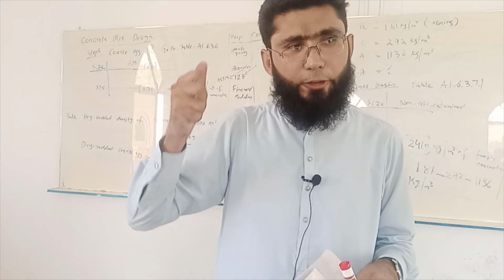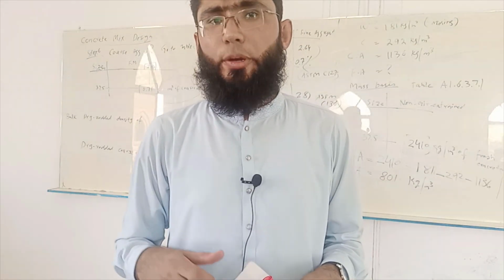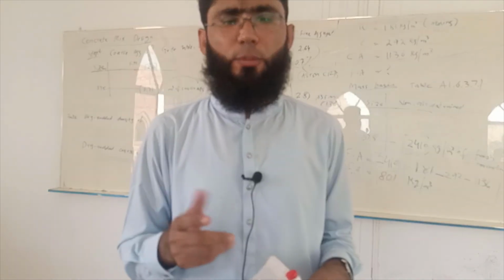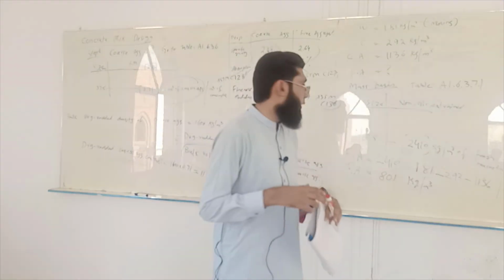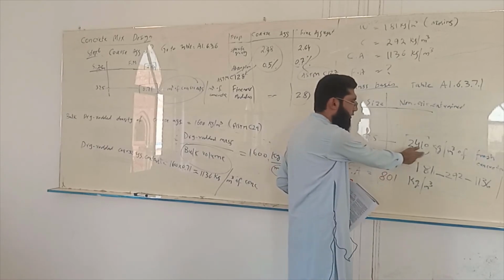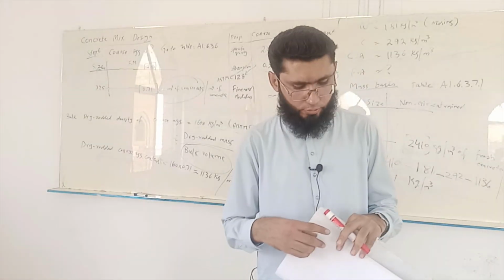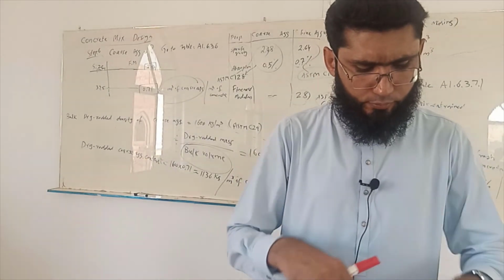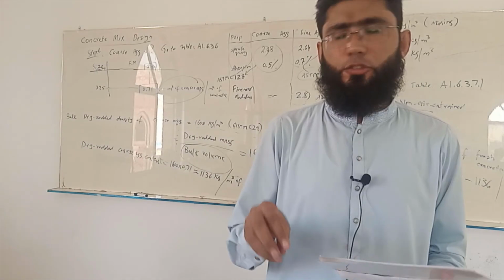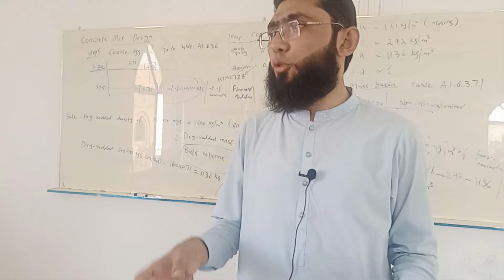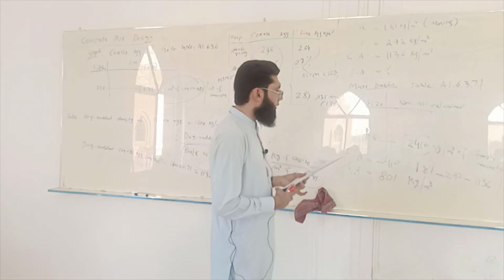Somebody will be pushing the concrete very hard while hardening, somebody else may be milder. Somebody may use a vibrating table. In fact, there are different guidelines that you need to use when you find the fresh density of concrete. They're given in that standard. I need to see that standard, but anyway, you better use the same method of vibration, same method of consolidation that you will be using for your actual mix, because that way you can get a more accurate value.